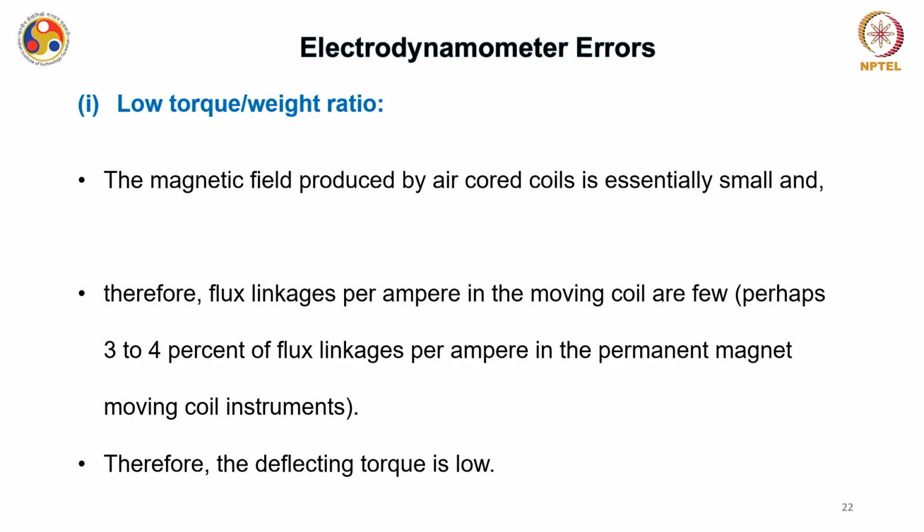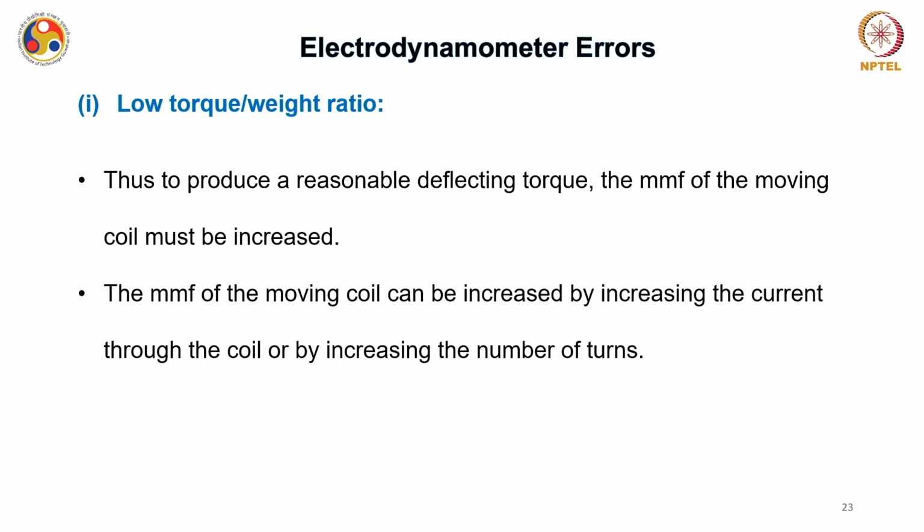So the deflecting torque is very small. Therefore, to produce a reasonable deflecting torque, the magnetomotive force, sometimes also called MMF, of the moving coil has to be increased.